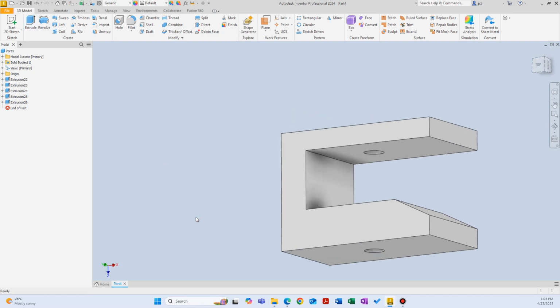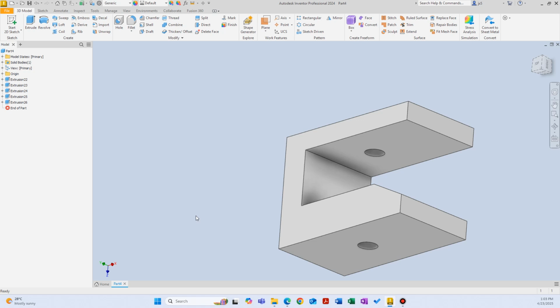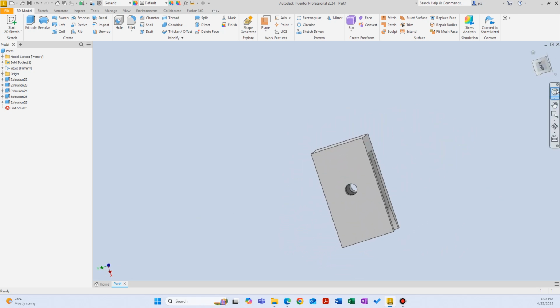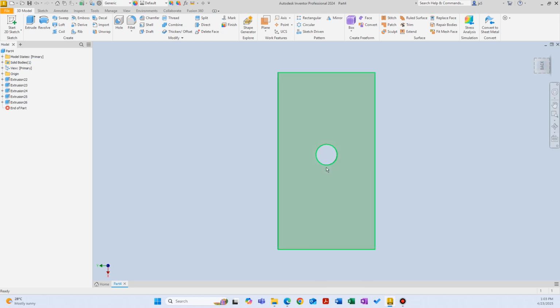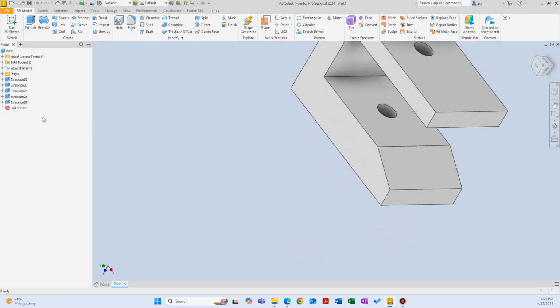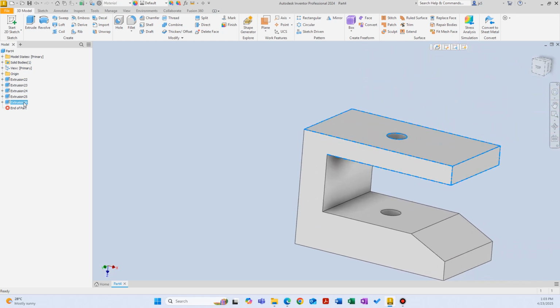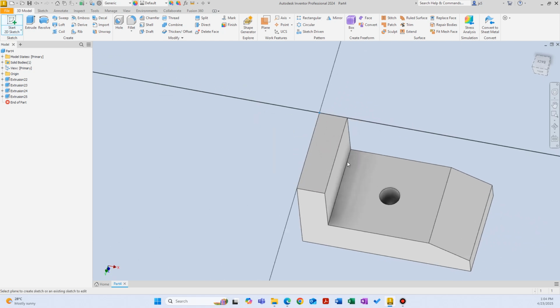Notice that I created this geometry by just taking advantage of the initial geometry I created. And that saved me a lot of time and made sure that everything is aligned. Now I know that this hole is completely aligned with this hole at the bottom. So now let's delete this final extrusion and maybe just modify the geometry, not only project it, but also after we project the geometry, let's add a few more circles and rectangles and lines, so we can modify the sketch and we can extrude that too. So let's delete this extrusion and create a new sketch here again.